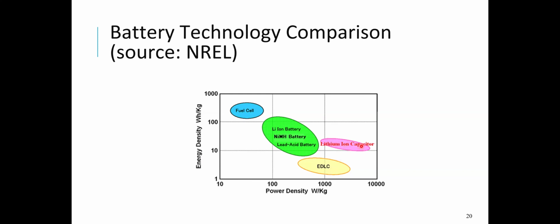And over here, I have some kind of a combination between a battery and a supercapacitor, or ultracapacitor is another name for it. These are lithium-ion capacitors, and that's a technology that's still in development. So lithium-ion batteries, as you all know, are kind of winning the day right now because they're reasonably high on this plot, they're reasonably inexpensive, and they have a relatively high cycle life, a long life. All right, so Ragone plots, very cool way to compare different battery chemistries.